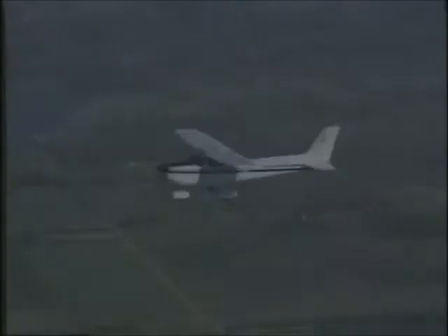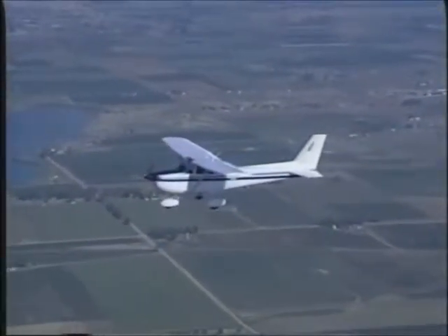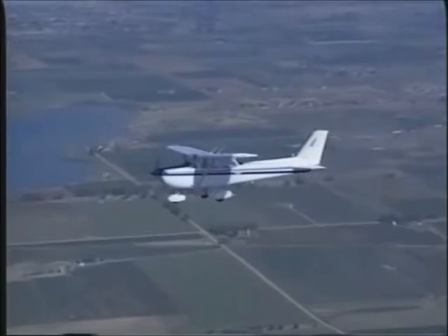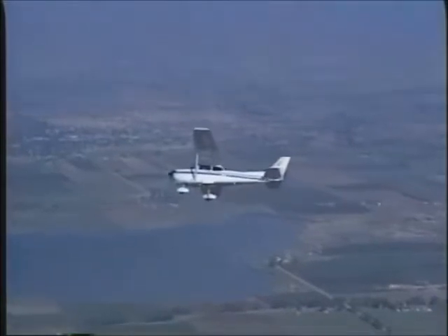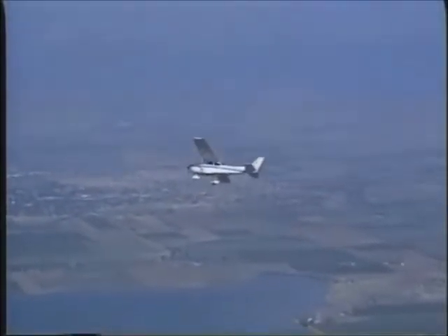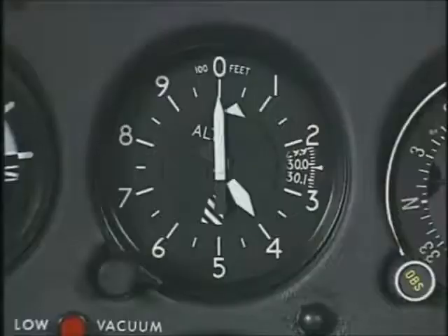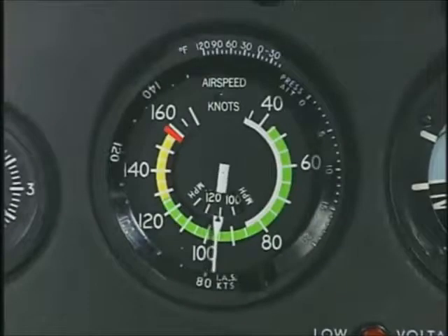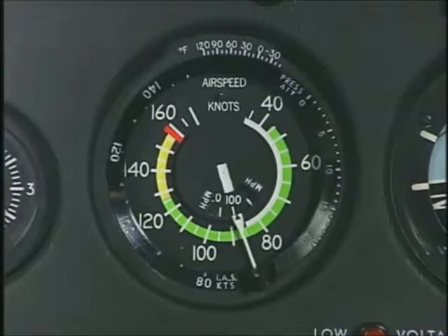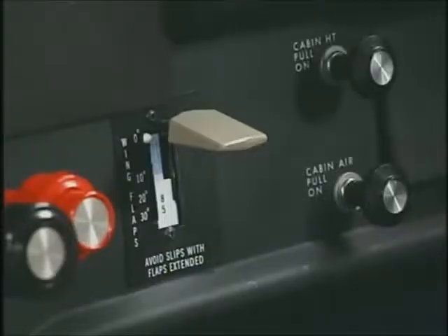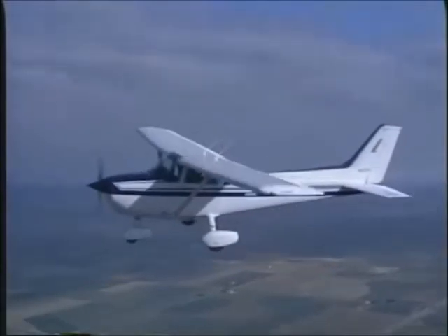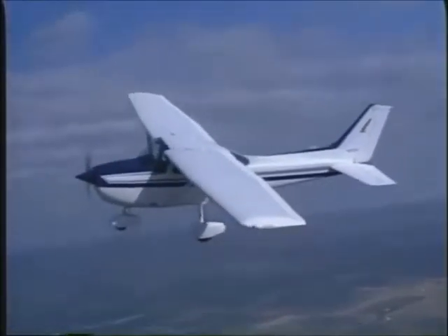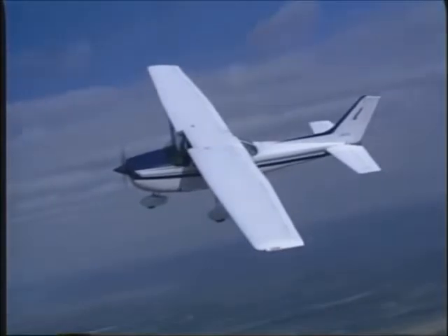Stalls should be practiced at an altitude that will allow you to safely complete the stall recovery no lower than 1,500 feet above ground level. For this demonstration, we'll check the area for other traffic, reduce the power, then maintain altitude until the airspeed approaches the normal glide speed. Flaps should not be lowered during this demonstration because of the possibility of exceeding the airplane's limitations. Once the glide attitude and airspeed have been stabilized, roll into a medium bank turn to simulate a final approach turn with an overshoot to the center line of the runway.